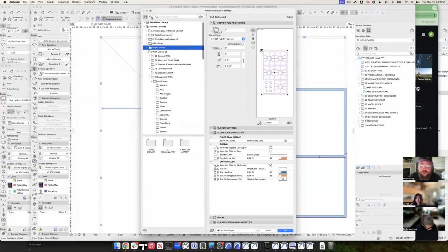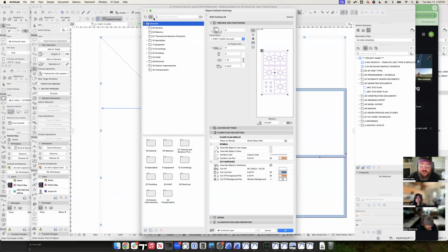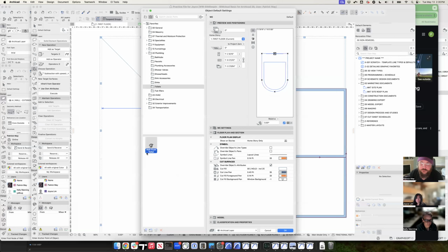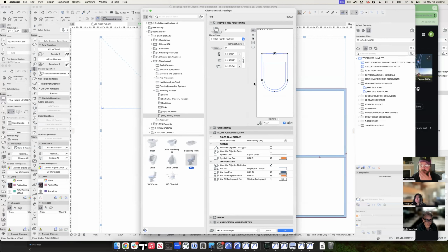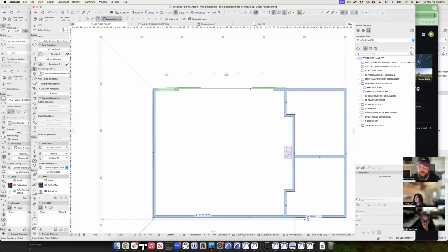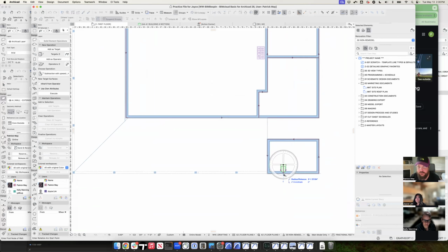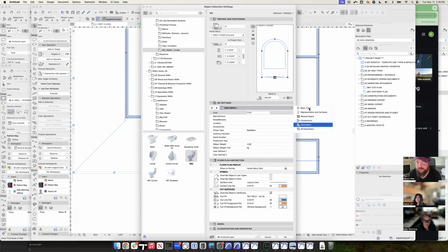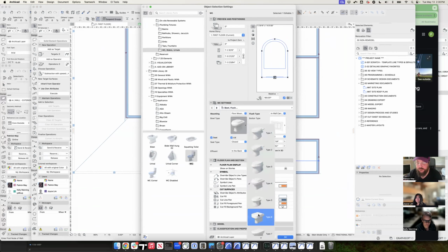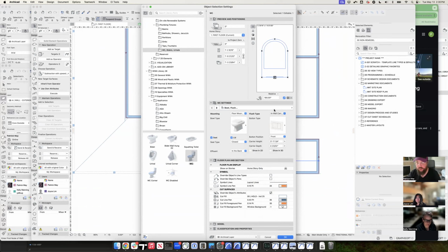If it's in the object library and we want to use it, typically it's saved as a favorite. So again, that star icon. Like plumbing fixtures and toilets. This toilet object is actually using the toilet from the out-of-the-box object. We just have it set with favorites to use the correct pens and fills. If we dump that in here, there's a toilet. The reason we use this instead of our own custom is because it has a lot of different configuration options. We can change what the bowl looks like, how it's mounted, hung, whether it has the lid or seat, and wall carrier, different options to make it pretty flexible and versatile.